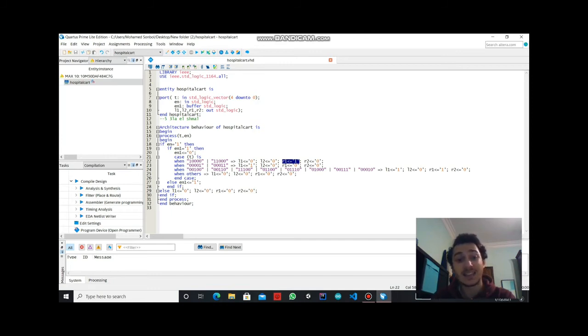The other case is the exact opposite, so the line is curving towards the right and the sensor is sensing it in its rightmost or two of its rightmost sensors. So we do the exact opposite. We set the output concerned with the left motor moving forwards to 1 and all of the right motor's outputs to 0 to make it stop. So the right wheel stops and the left wheel moves forward, basically creating a right turn.